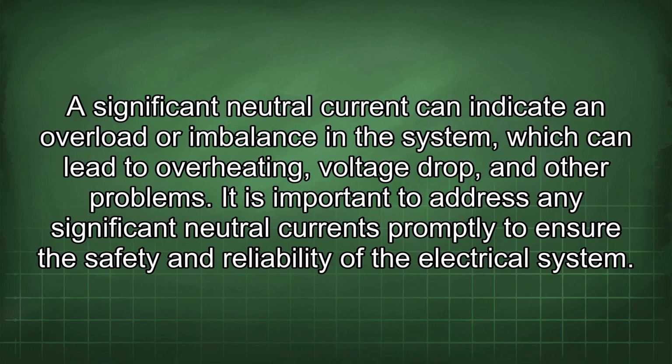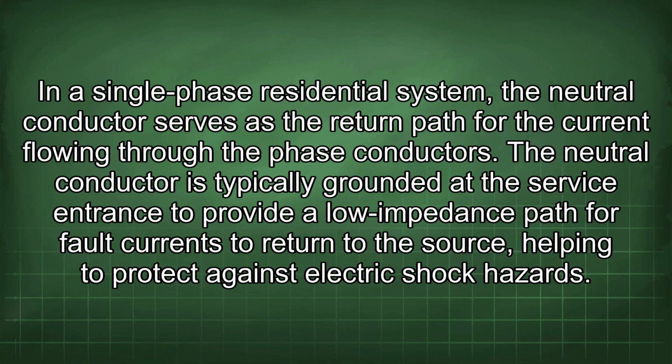In a single-phase residential system, the neutral conductor serves as the return path for the current flowing through the phase conductors. The neutral conductor is typically grounded at the service entrance to provide a low impedance path for fault currents to return to the source, helping to protect against electric shock hazards.